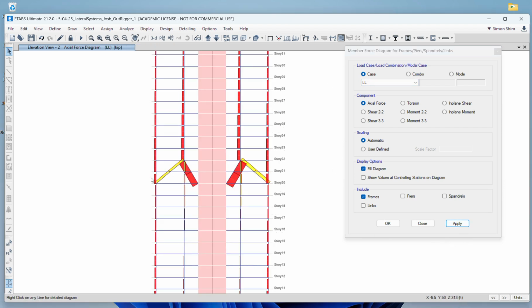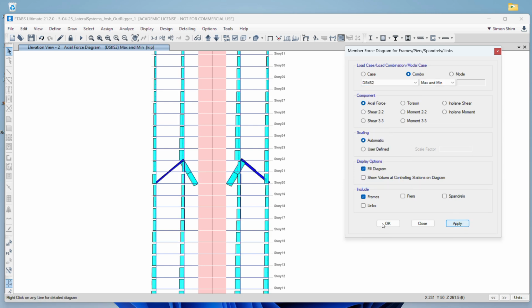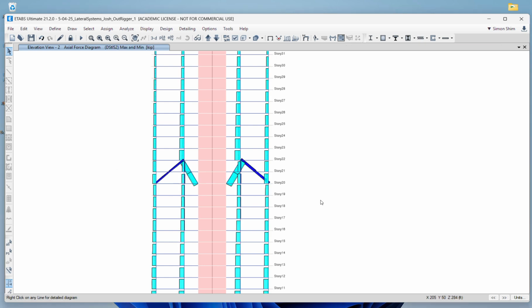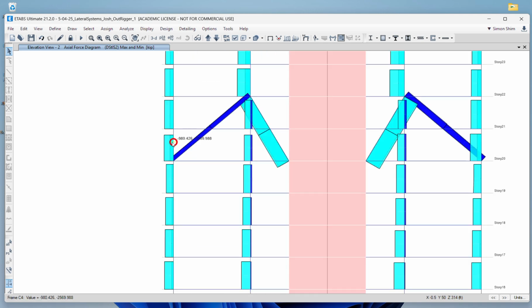with this diagonal member. So obviously you may consider this a load distribution due to the dead load and the live load. But when you combine the entire load combination for final strength design, you see all these forces, right? Yes, still we have some issue. The dead load was composed dead load and live load. Okay, live load is pretty significant. All right, so still we have some issue here.